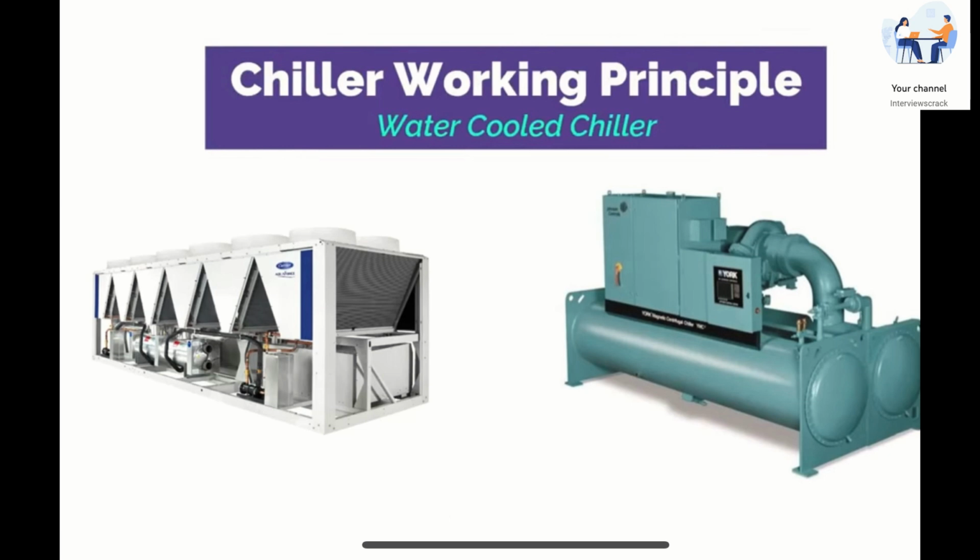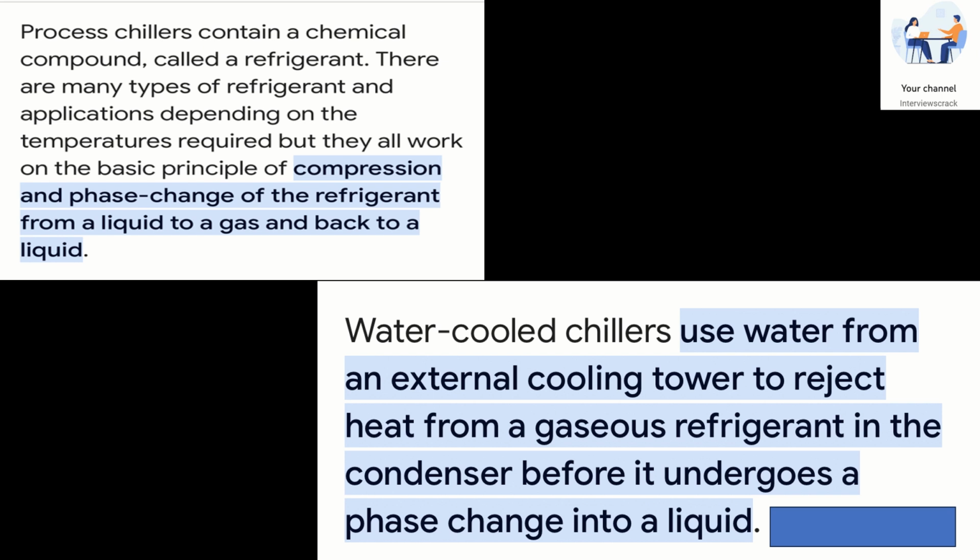Hi friends, today we will see what is a chiller and what is its working principle. Today we will see the water cooled chiller. What is the working principle? It works on the principle of compression and phase changes of refrigerant from a liquid to a gas and back to the liquid phase.